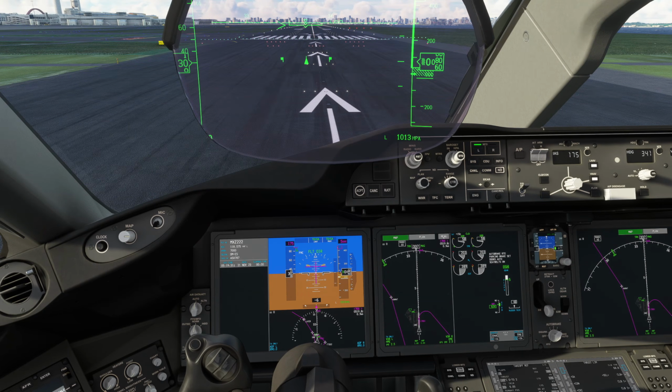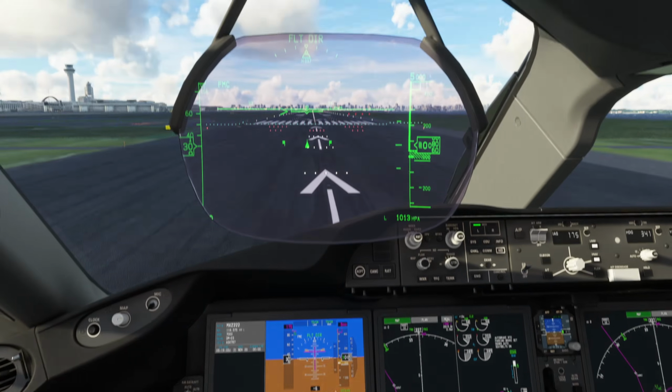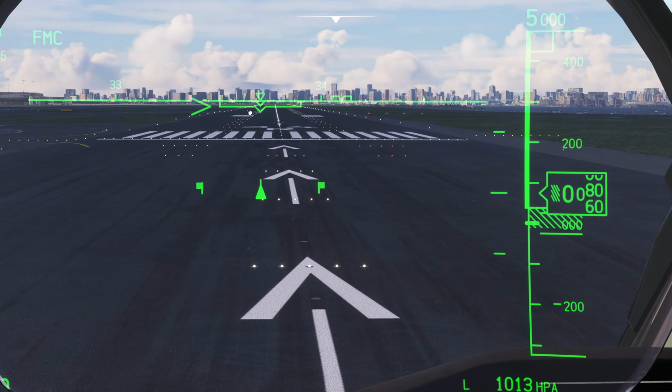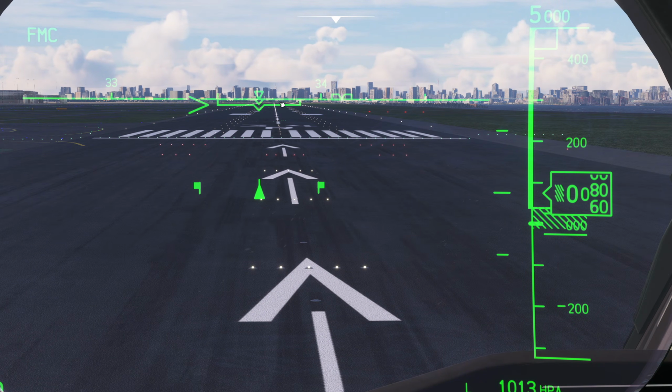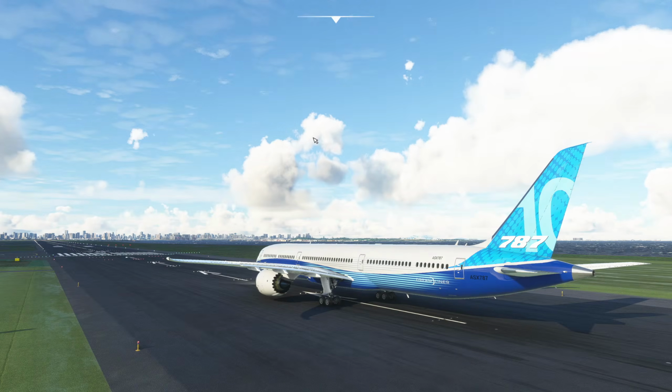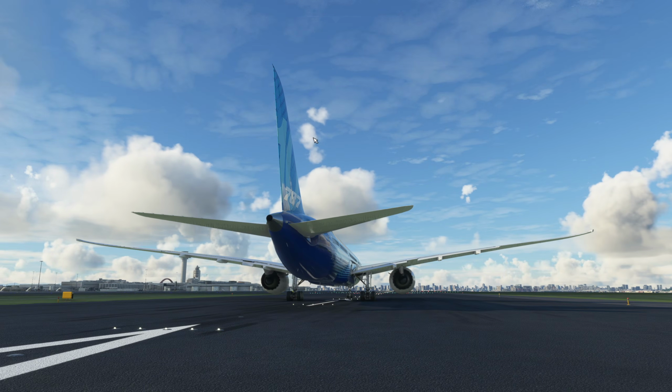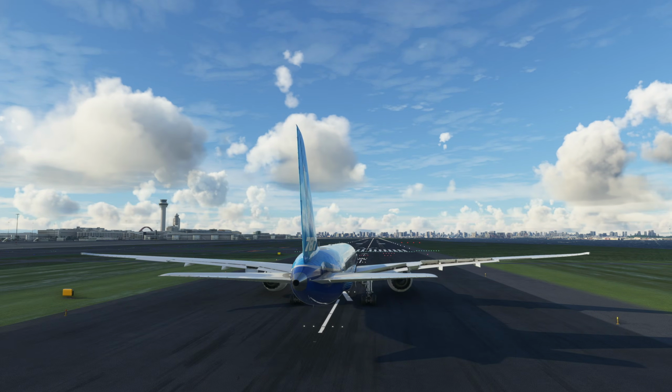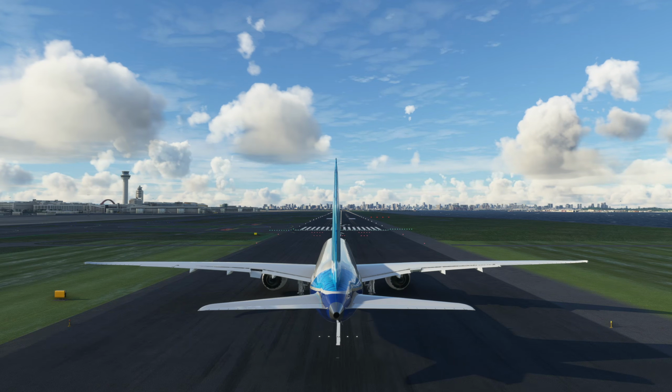As we roll down the runway, I'm going to keep the airplane level. The easiest way, frankly, is to look here and see if this bar is level. If it's not, then you might need a bit more aileron or a little bit less, depending if you put too much in. As you do that, of course, remember that as you use the control more and more, you'll eventually get spoilers up. The roll spoilers will deploy on that wing.